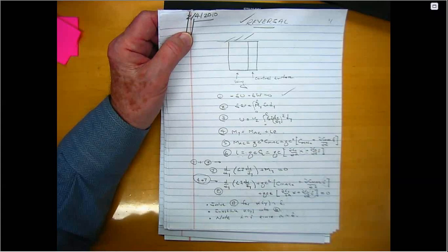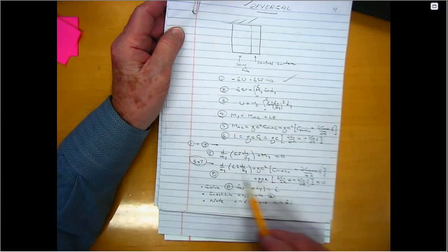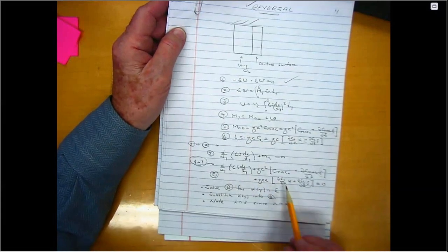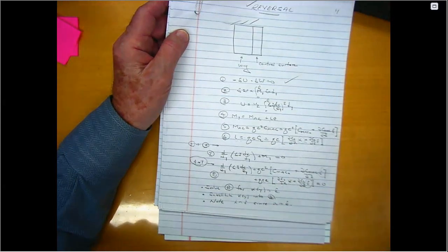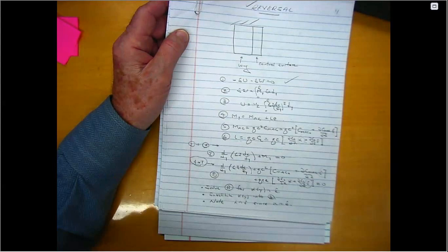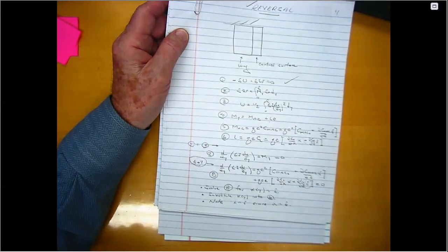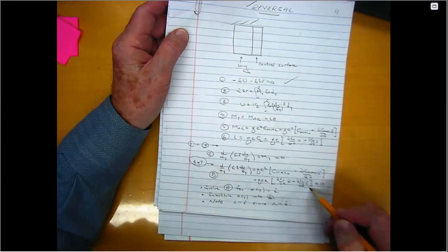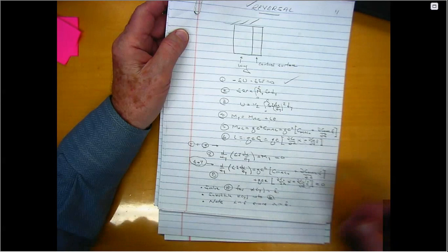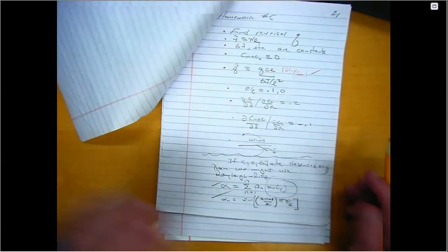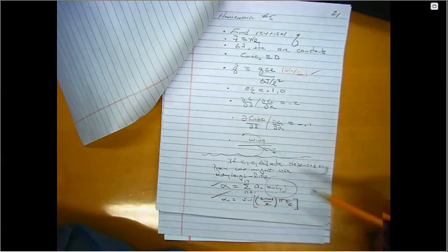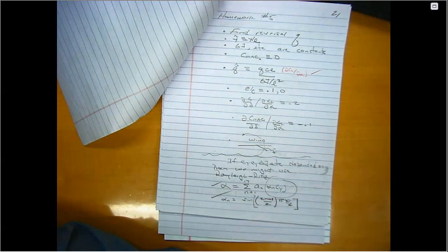But remember, if all these parameters are constant, if GJ and so forth is constant, then you should be able to solve this differential equation analytically, in terms of sines and cosines of y. Plus that. So that will be the homogeneous part of the solution for alpha, and then there will be an inhomogeneous solution, which depends on delta. On the other hand, you could solve this problem by using Rayleigh-Ritz. You could take alpha and expand it in terms of some modes, and I suggest that these modes be some of the modes that satisfy the boundary conditions. That's always a good set of modes to use.